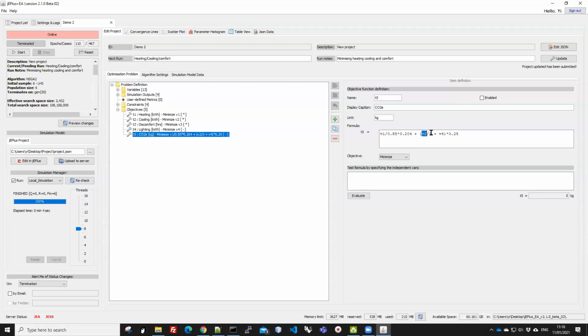And the next part, V2, is cooling consumption divided by the efficiency of your cooling system. That's constant here, which means annual COP is 3. So this gives you an electricity consumption. Plus V4 is actually lighting, but we're not looking at lighting right now, so you could remove that.